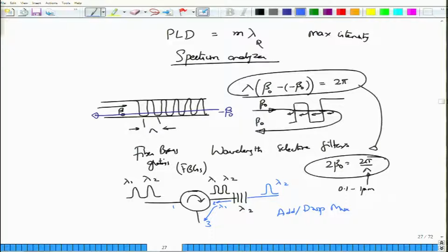Fiber Bragg gratings are also quite sensitive to temperature; in fact, they are used in temperature sensors. They are quite sensitive to acoustic phonons in the fiber, so they are used for acoustic sensing. Fiber Bragg gratings are used in general for the structural health monitoring of buildings. It has a lot of uses. Most sensors use fiber Bragg gratings in one form or the other.